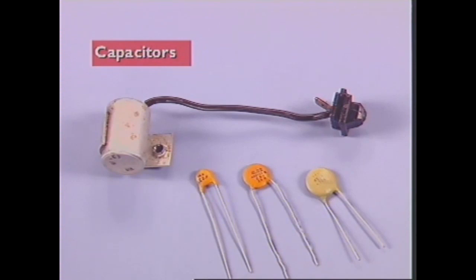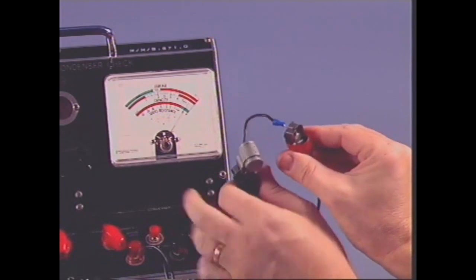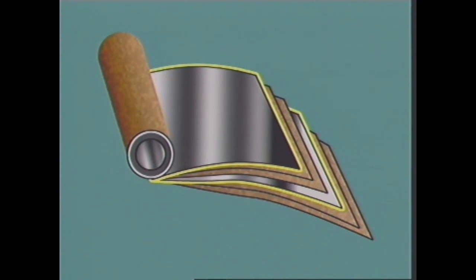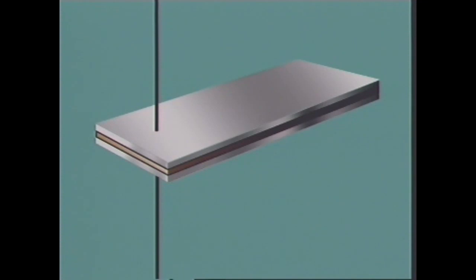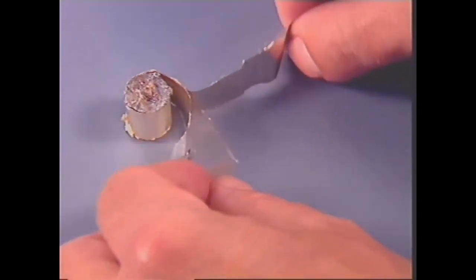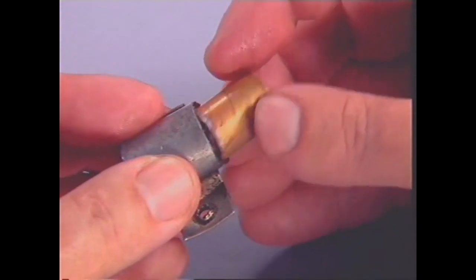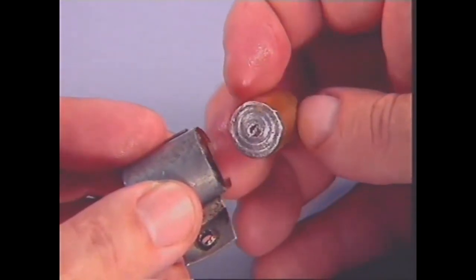This section examines capacitors. A capacitor can quickly store a small amount of electrical energy. It's then said to be charged. Inside are 2 surfaces, separated by insulating material. When the capacitor is charged, one surface is positively charged, the other is negative. When a circuit is closed between its terminals, the capacitor releases charge. It is then said to be discharged. A typical capacitor stores the charge on thin sheets of foil with sheets of insulation between them. These are rolled together to form a protective canister.